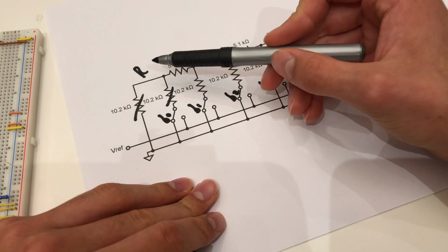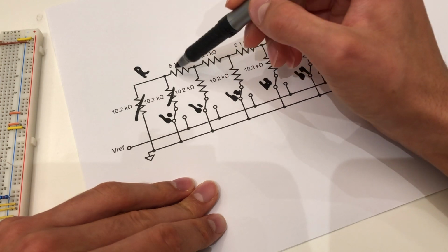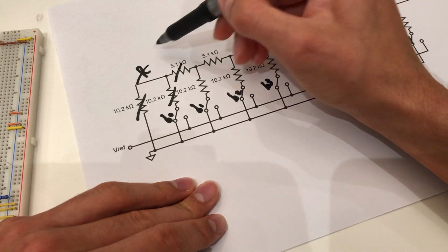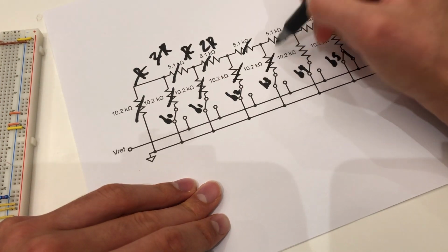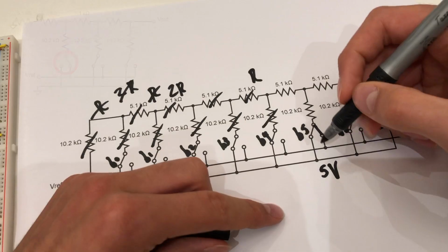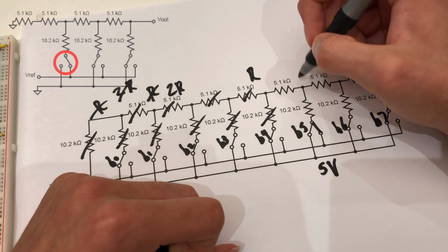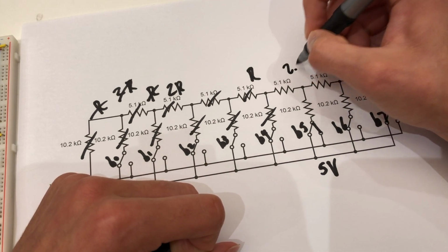We simplified these two, and now we have the exact same thing again. So these are 2Rs, they simplify to 2R, where all of this circuit here can be simplified to just R right here. Now what we have is 5 volts here, and since there are 2 resistors of the same value, in the middle here this is going to be 2.5 volts.